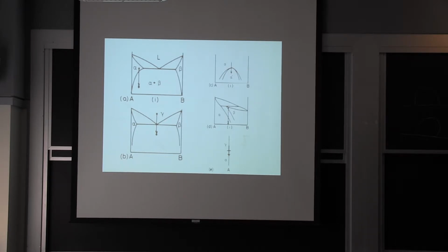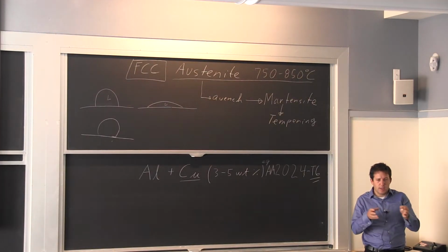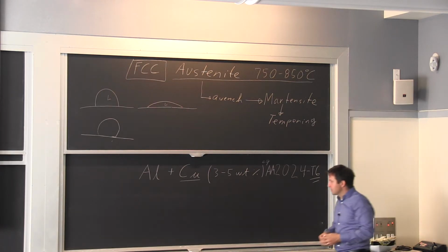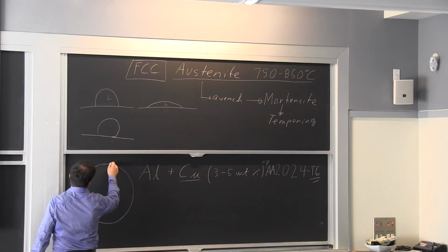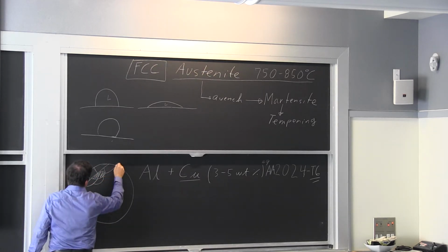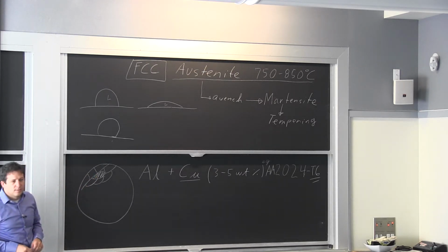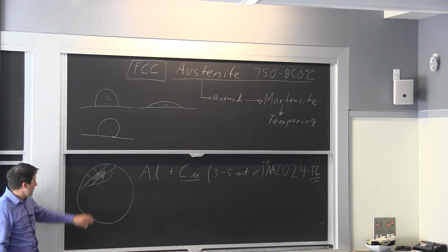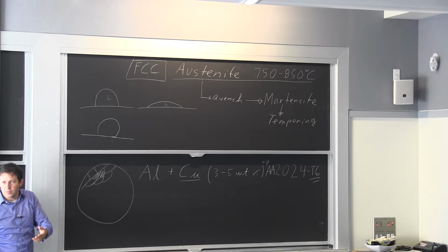That doesn't give us much good, and I'll explain a little bit. So if I have a microstructure that has aluminum and 3% copper, and I'm just looking under the microscope at something with a lot of grains, and I have a very hard one surrounded by a bunch of soft ones. This is a little bit like a piece of wood in the river, a floating log. It's not going to change much of anything in the flow or anything that's going on. It's just going to be carried with everything else.